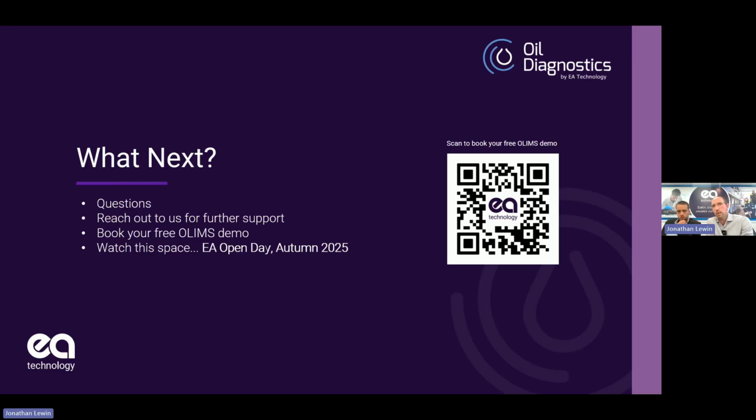If you look at mineral oil, for example, it has been around for a very long time. There's a lot of information about it. There's a lot of IEC methodologies. There isn't the same methodology for the newer fluids. They will come in time, but as it stands, there isn't. So the best thing to do when you've got an FR3 is to use a similar kind of application, but the gassing's different, so interpretation will be slightly different depending on the fluid type.